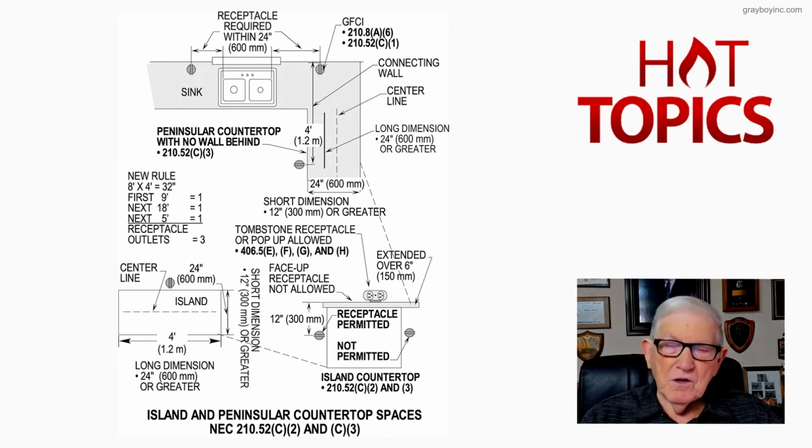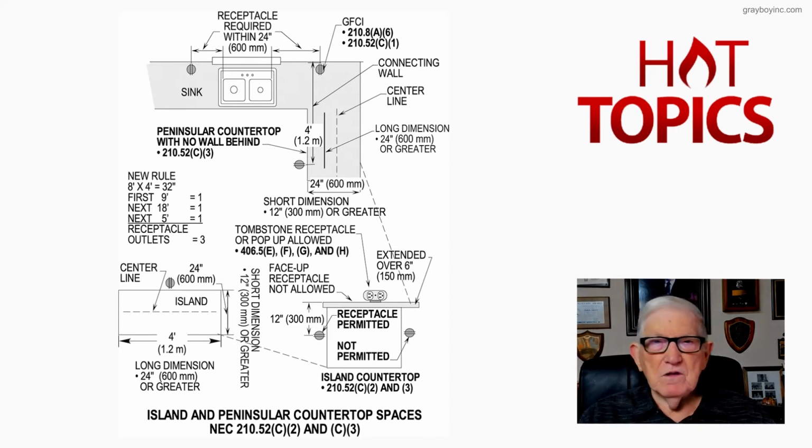And then this is very important, I think, next, for the purpose of this section. We're using multi-outlet assemblies, 12 inches of multi-outlet assembly, with one or more receptacles shall be considered one outlet. In other words, you couldn't just put a multi-outlet assembly there and say, okay, we have the 3 or 4 outlets required by this section when you do the math, as we'll see coming up.